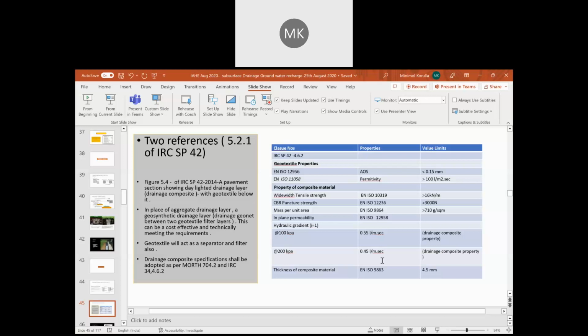If we are doing a sieve analysis of the sand gradation, d1 is the aperture size of the sieve through which the fraction passes, and d2 is the aperture size of the sieve on which the fraction is retained. From these d1 and d2, we get D, which is the mean particle diameter in millimeters.